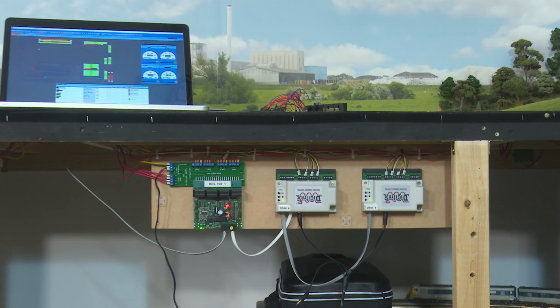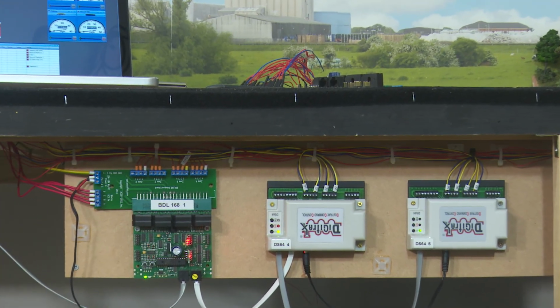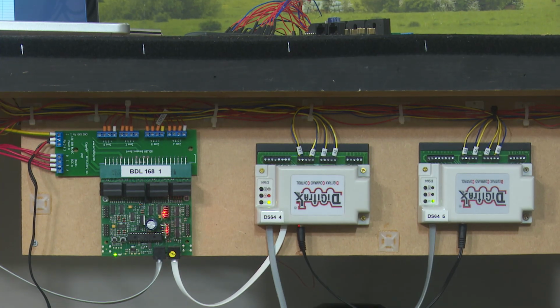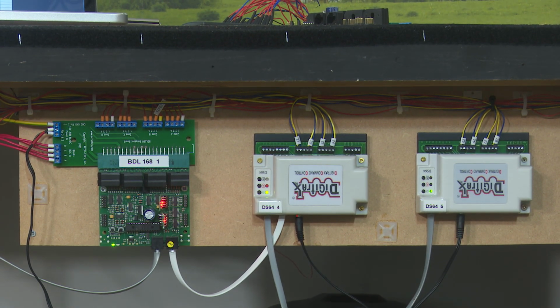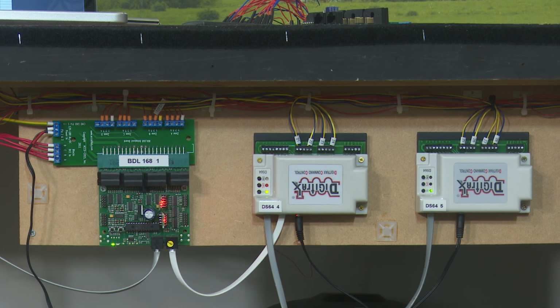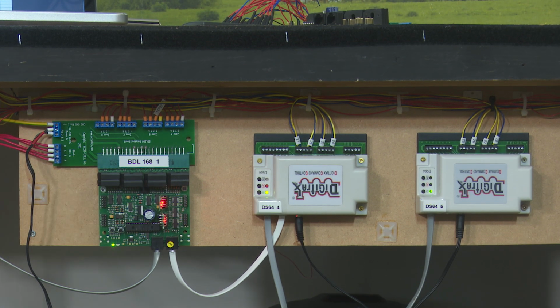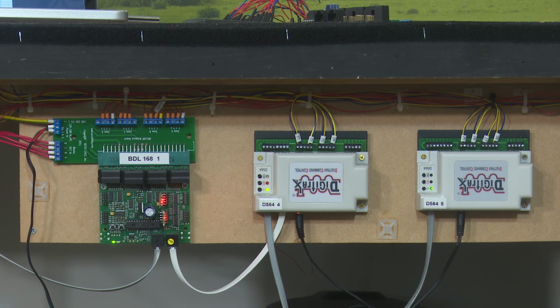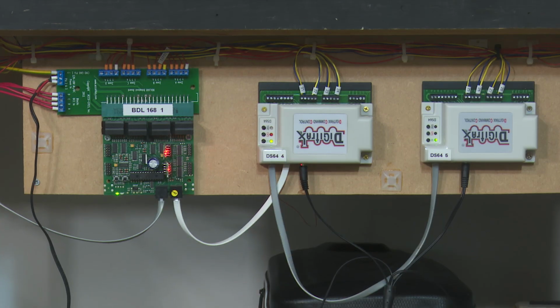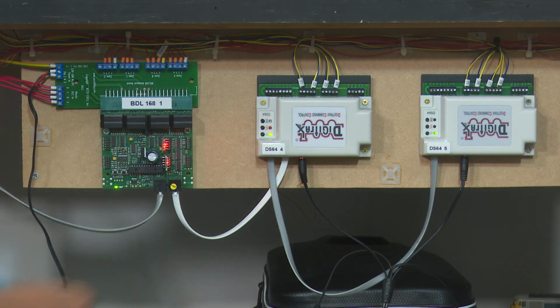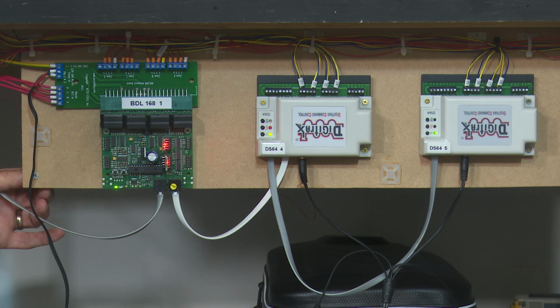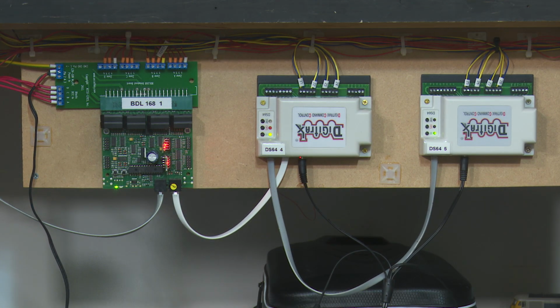Well, hopefully that seems straightforward, but of course it does leave you with the issue, how does all this information about occupancy get back into the laptop? Well, that's done by a system known as Loconet. So now, looking underneath the board, we'll see one of my little drop-down boards which contains a couple of DS64s which control the points there, and also a BDR168 which I've labelled as number 1. And hopefully you can see that between these items is daisy-chained a cable. It's a 6-core cable, and it goes back to the controller DCS240 and then via USB up into the laptop and then into train controller.